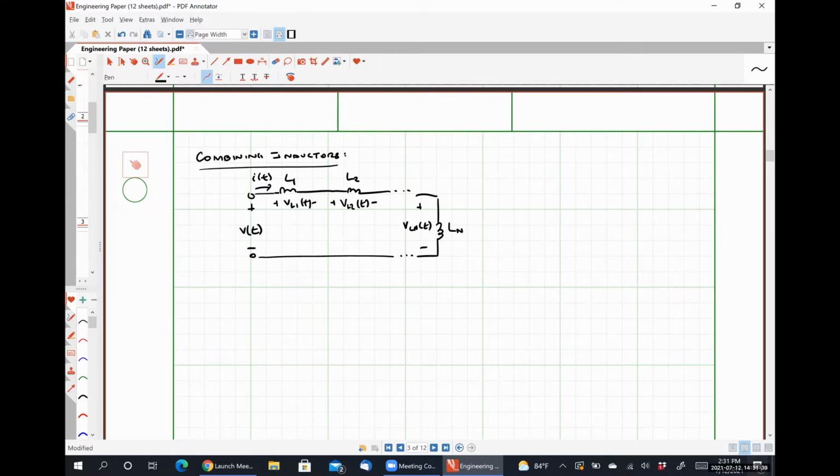In series, you do their reciprocal, and then in parallel, you add them up. So in series, adding the reciprocals, that was how a capacitor behaved, right? But the capacitor is the opposite of the inductor. So for those of you who didn't attend class on Thursday, we found out that capacitors in series combine like resistors in parallel.